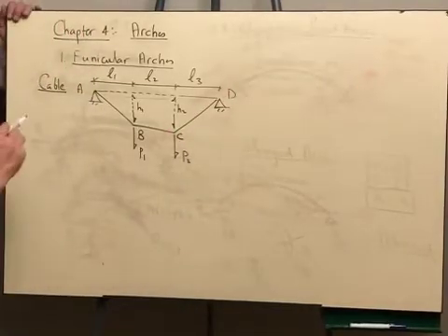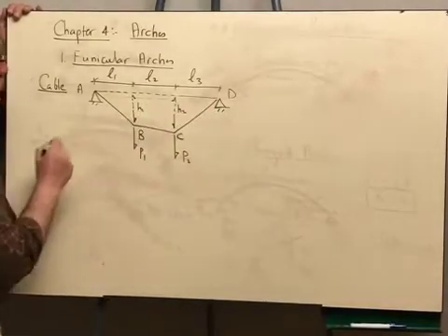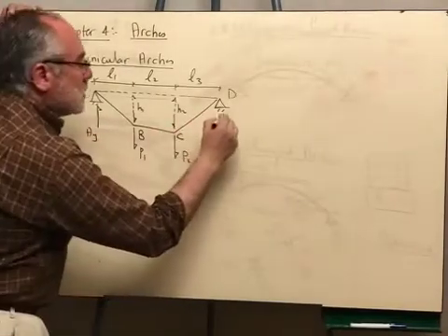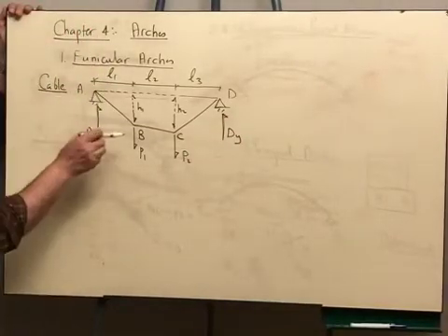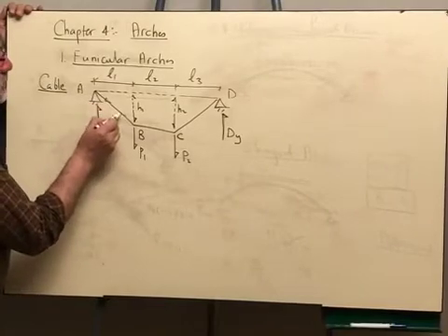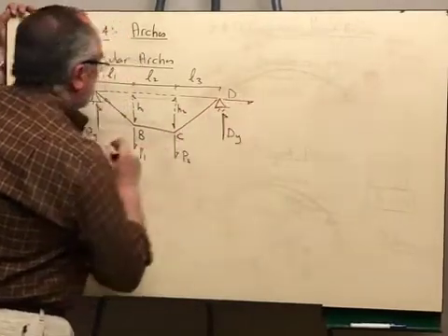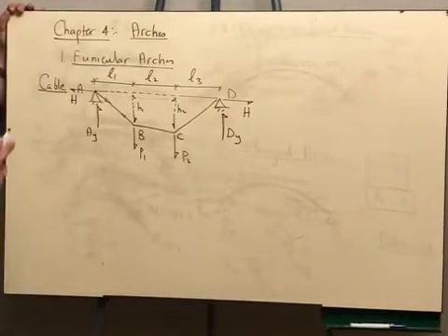Now, because this is a cable, it cannot support any internal moment, as we said before. So any point is considered as an intermediate hinge. So I can take moments about point D to determine the reaction AY. Sigma Fy is equal to 0. I should be able to determine the vertical reaction DY. Because this is a cable, we are having tension here. So therefore the horizontal reaction should be outward like this. Every point qualifies as an intermediate hinge.